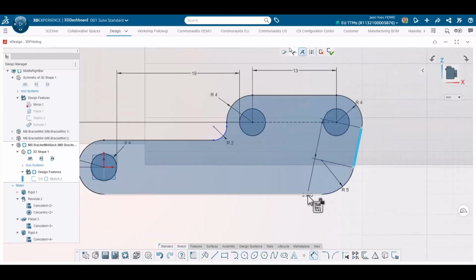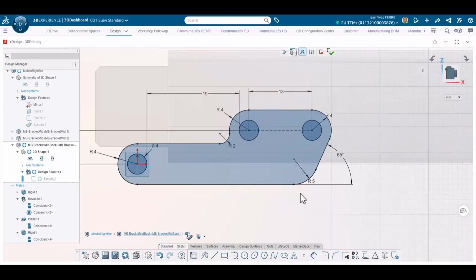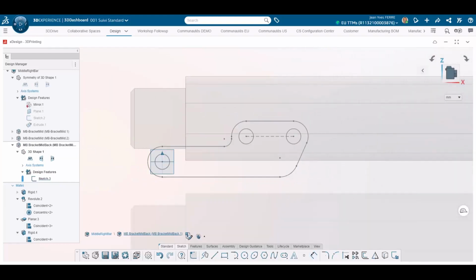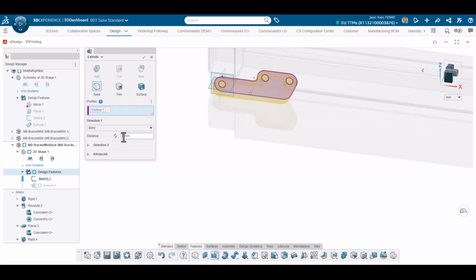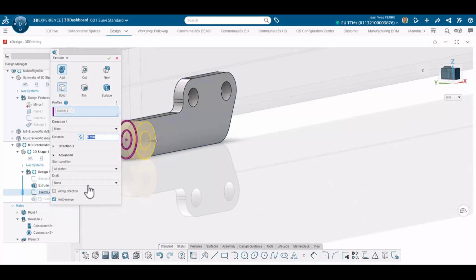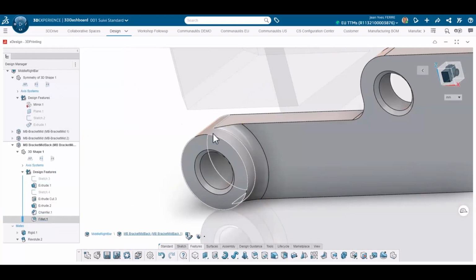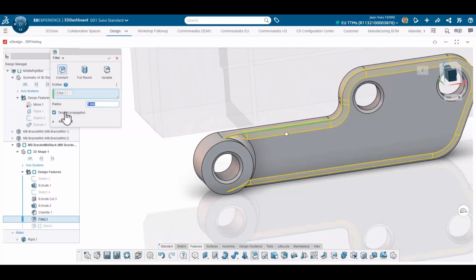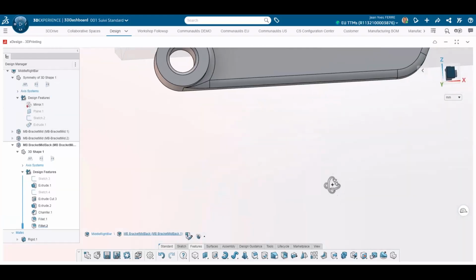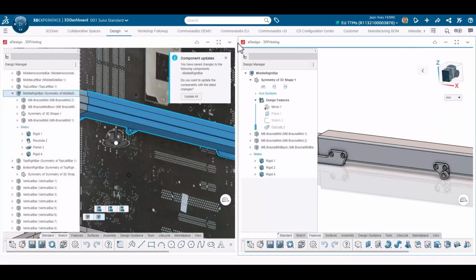and I add an angle to build material only where it is really needed for part strength. Once the sketch is finished, I create a 2.5mm extrusion and a 2.5mm boss for the mounting hole. I also finish up with some fillets, and the middle bar now has all mounting holes aligned correctly to secure the motherboard on the structure.